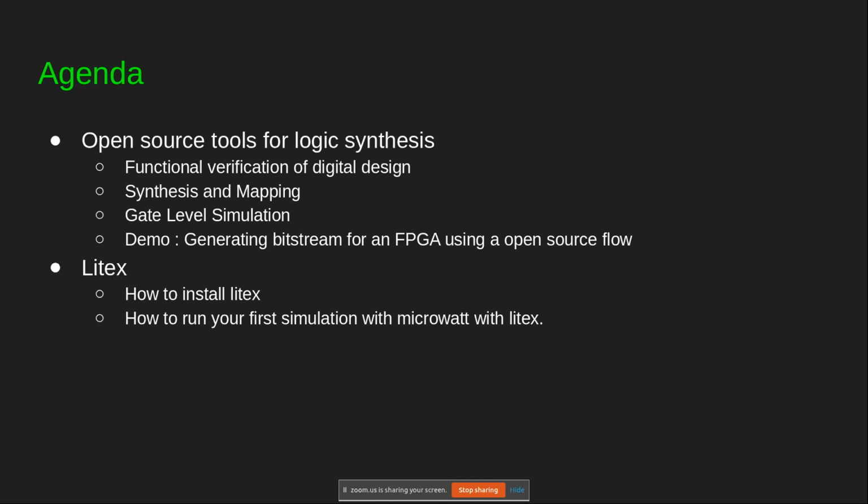I'm also going to show you how you can use the same flow to target a cheap FPGA that you can buy off the shelf. In the end, we're also going to talk about LiteX, which is a framework for generating SoCs, and I'll also show you how you can simulate an SoC which uses Microwatt as the CPU.